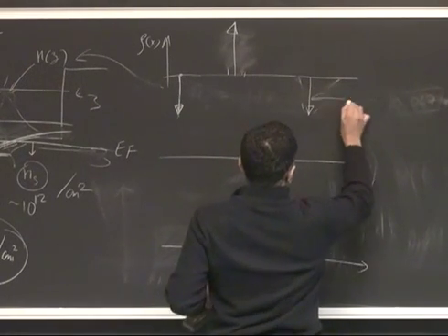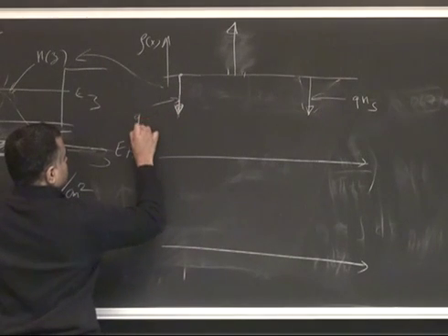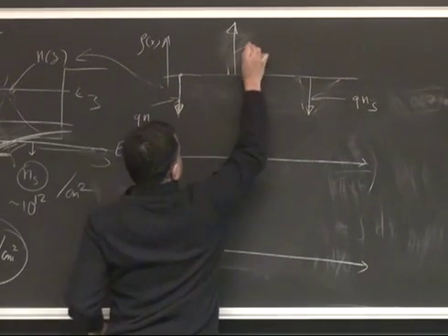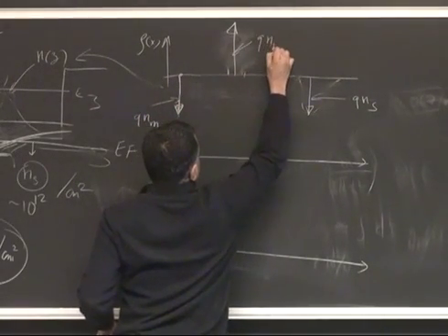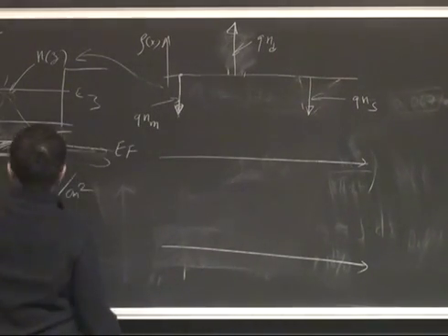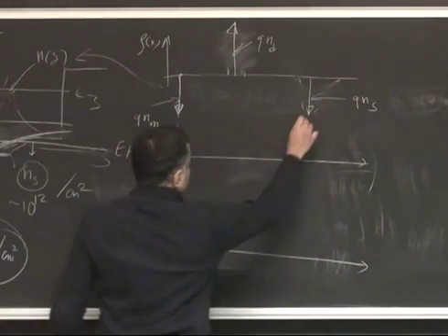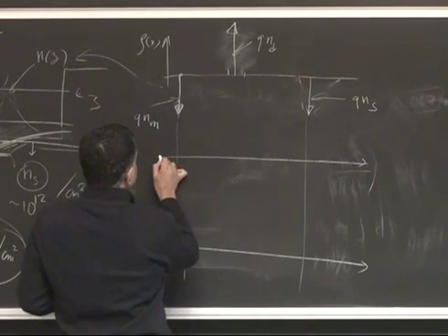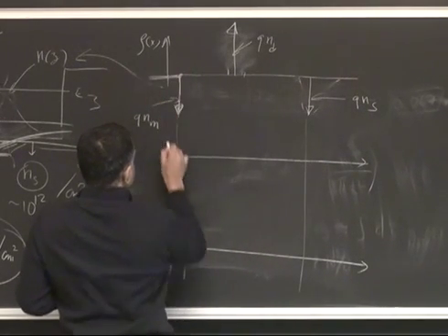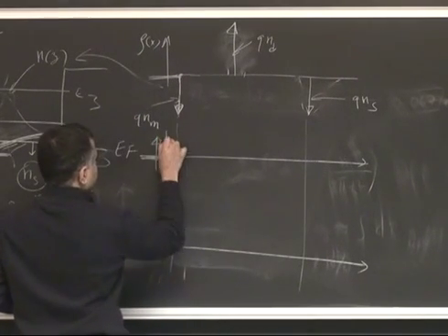And that's going to be my Q times N sheet charge in the quantum well, Q times N in the metal, and Q times N dopant. Right? You can kind of break it up like that. And that immediately you have a relationship between them now. But now going down here, you see in terms of electric fields, deep inside the metal, left side, the field is 0. Right? We're going to plot the electric field now.